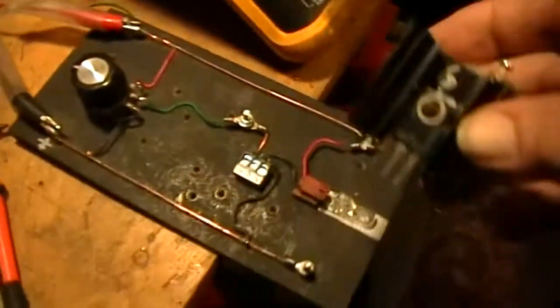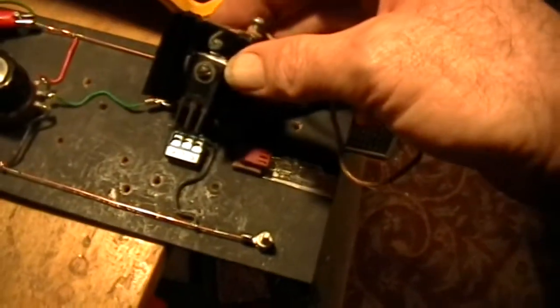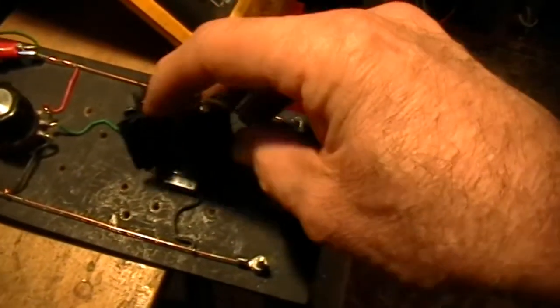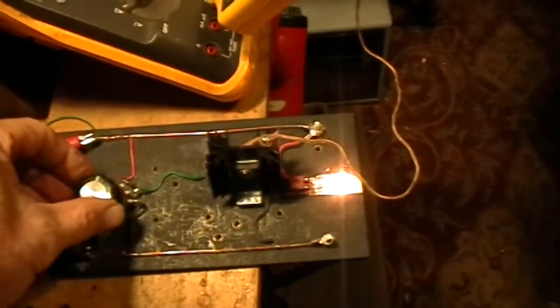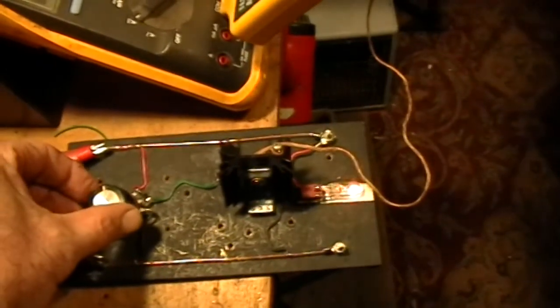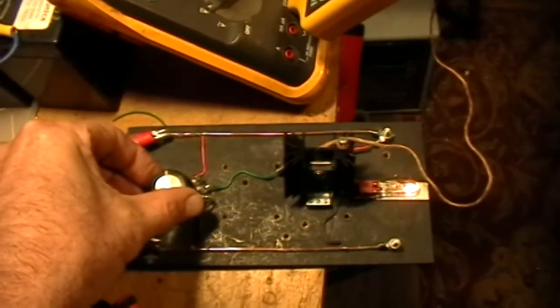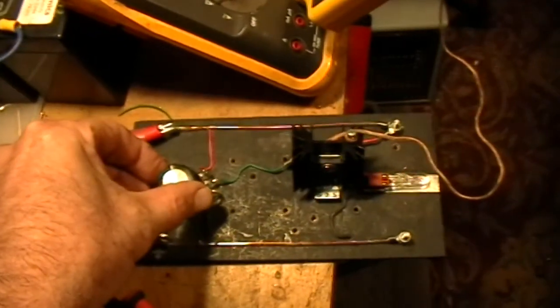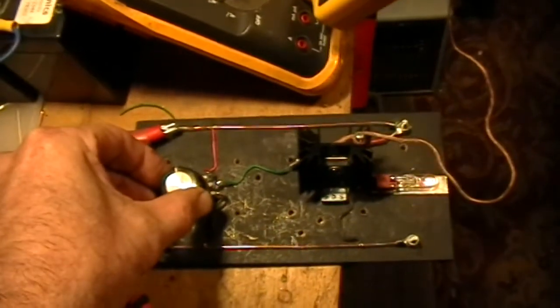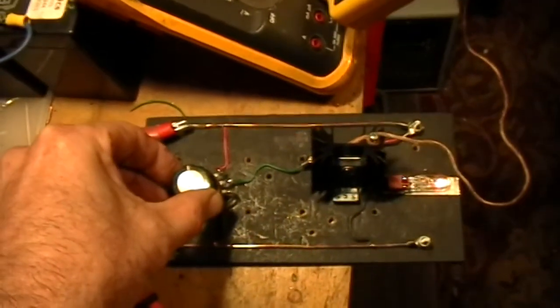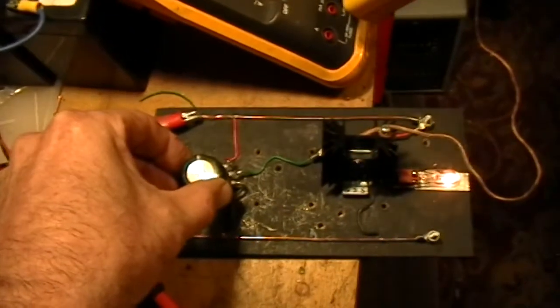So I take it over to my test bed here and I just stick it in the socket, and then make sure we're giving it 12 volts, and then we crank the knob until we get a light, and then we make very, very small crankings of the knob to make sure that the MOSFET is still operating in the linear conductance region, or can operate like that.